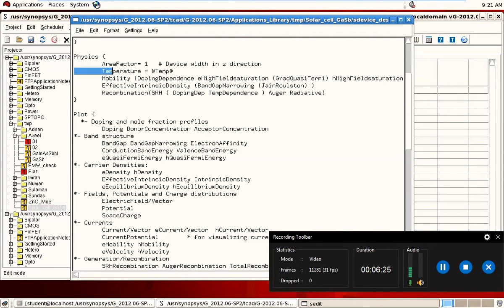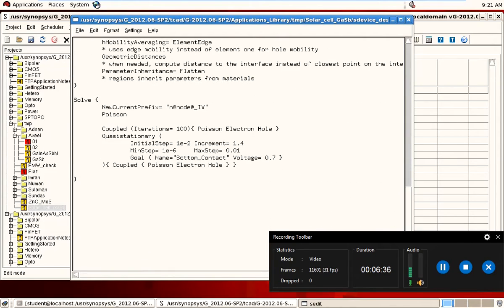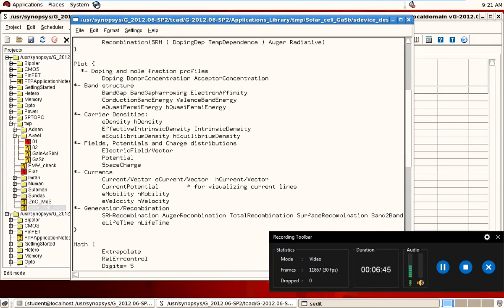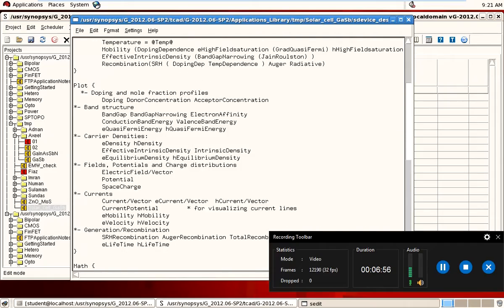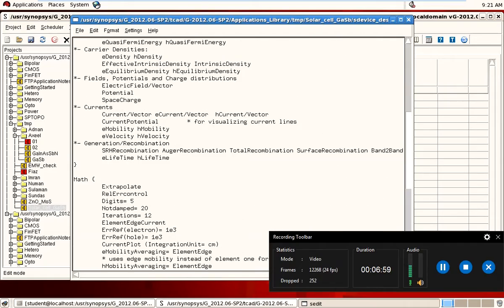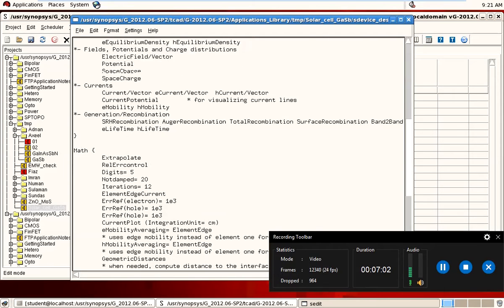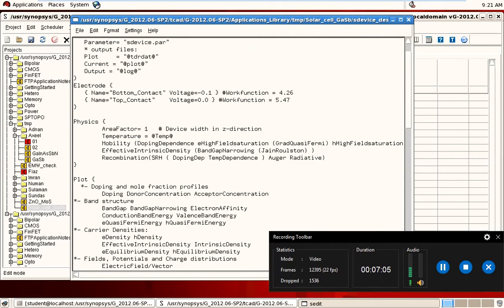There are two other ways to find the overall device temperature. We can use the hydrodynamic model and the thermodynamic model for this purpose. If we use the hydrodynamic, then we define the electron temperature here, and if we use thermodynamic, then we only define the temperature here. Secondly, we can add the temperature plot for the simulation, but here we use the diffusion model based upon the temperature effect. So therefore we don't need an extra plot file for the temperature effect. Okay, so this portion is complete.